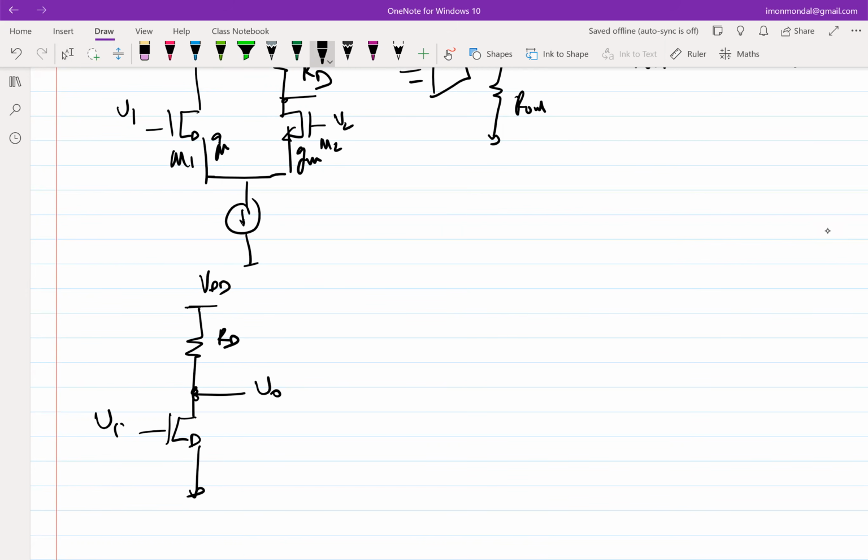Now, before going to the question, the problem we have encountered multiple times is that if we use this resistance RD and we want larger and larger gain, we have to increase VDD, right? We did multiple problem sets on this. We figured out what is the value of VDD or what is the value of RD that is required to achieve certain gain and so on.